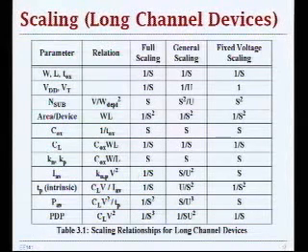Now we know that when your velocity is saturated, increases in voltage are no longer leading to a benefit in performance. And that is just a first order approximation. When you keep increasing voltage, you really have short channel effects and channel length modulation, and your performance does increase a bit, but this is really just a secondary effect. What we're really concerned with here is understanding the primary reasons why the scaling has been going on as it has been.